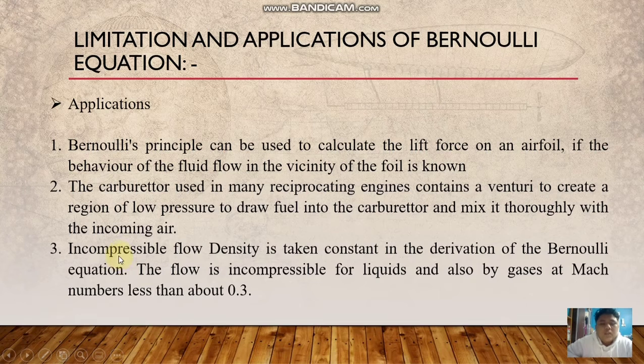And lastly is incompressible flow. Density is taken constant in the derivation of the Bernoulli equation. The flow is incompressible for liquids and also for gases at Mach number less than 0.3. So that's all for me.